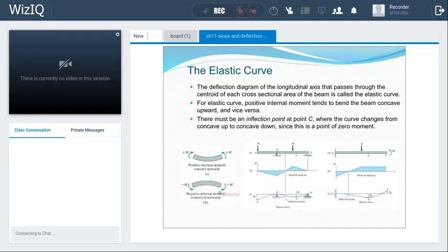that is concave downward. And if you look at these cases here, this is a part where you will find negative bending moment. And in the case of negative bending moment, the beam is deflecting in such a way that it gives you a curve which resembles this hogging, or concave downwards. In this part, where you see the bending moment is positive from this point to this point, you find that the curve is like this, which is sagging, or we can say it is concave upward.